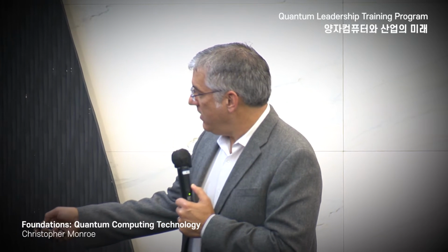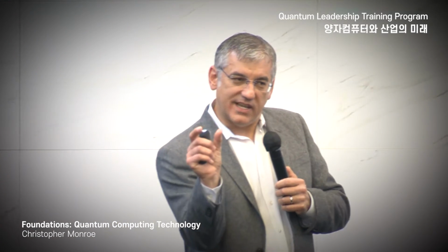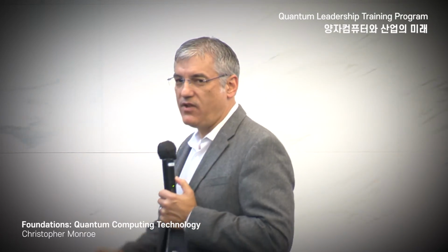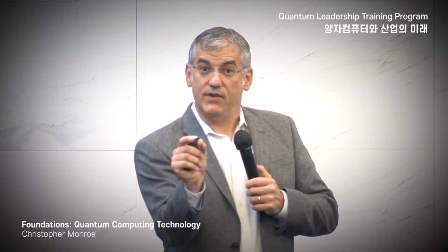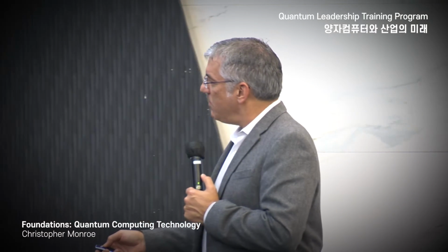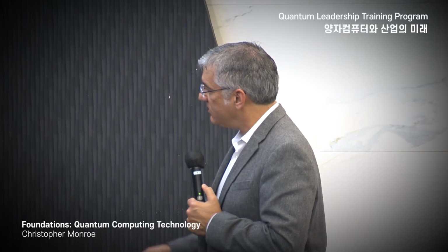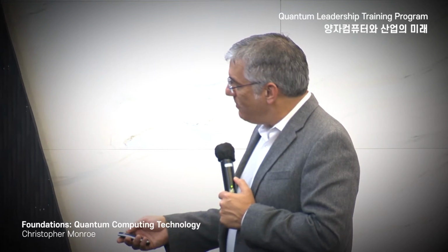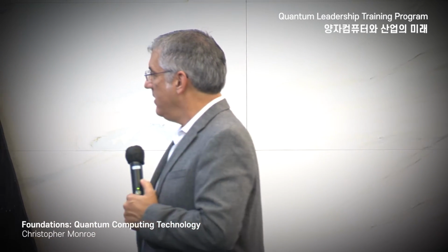You'll notice on this plot, in the last decade or so, it's tapering off, and we recognize this. It gets really hard to make transistors much smaller than about 10 nanometers. They're getting down there, but when you get below 1 nanometer, people don't really know how to do this. There will be all kinds of issues involving the granularity of materials, the individual atoms, and actually there are quantum effects that creep up there. So there's a problem in the scaling of Moore's Law to keep continuing this way throughout the 21st century, and it almost certainly won't.